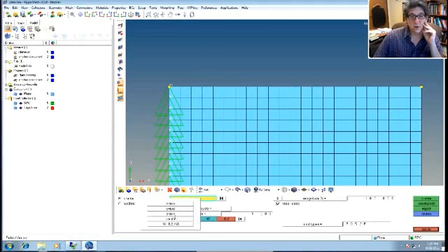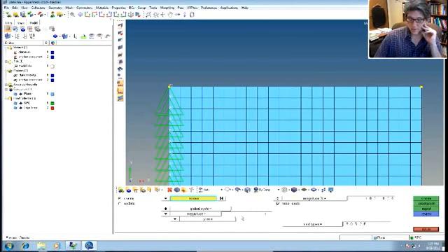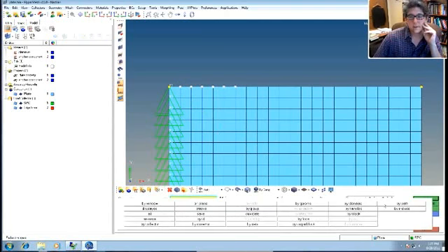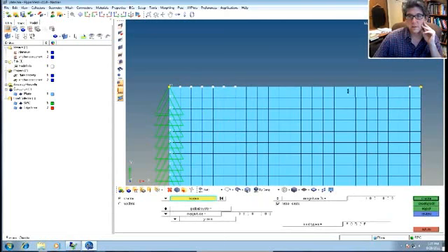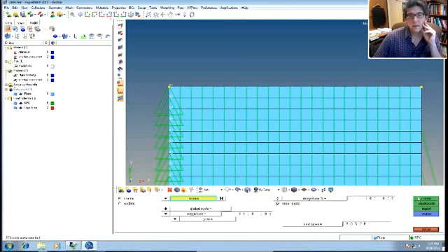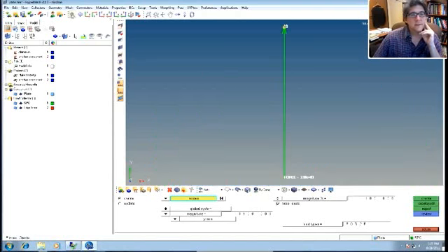So our forces are all going to go in the y direction. Let's pick the middle ones. These are going to have values of 3900. This one just scales the size, just like the size on the MPCs. And let's pick these nodes. I should do it by path. So I have all those. Create. All right. And there they are.